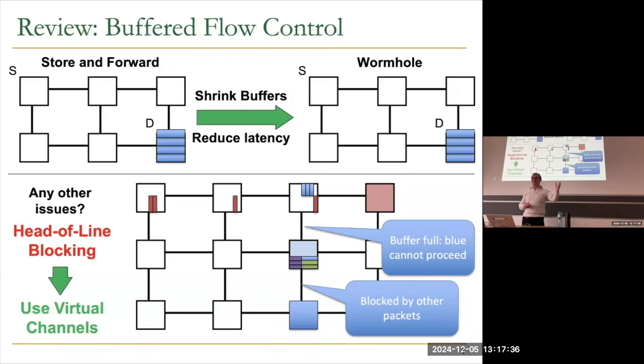So you can think of in-order scheduling, which is FIFO, and then completely out-of-order scheduling. You have to examine every single thing in your entire buffer to decide which packet can be scheduled to which destination, which port. Virtual channels give you complexity closer to FIFO, away from the out-of-order, by getting some of the benefits of out-of-order scheduling. So in DDCA, for example, we've covered out-of-order execution, right?